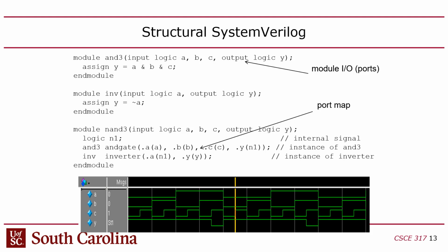So it's a great debugging tool. Now here's the problem. In 611, you would have used that if the simulator worked, if your design worked in the ModelSim, but didn't work on the FPGA. Then what do you do? You're done. I mean, there's nothing you can do. You're done unless you have the ability to see what's going on in the FPGA, and that's what you use